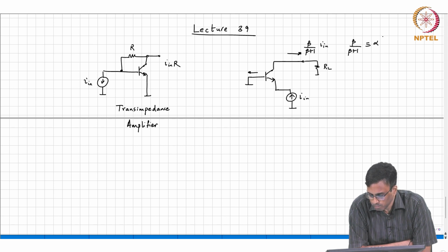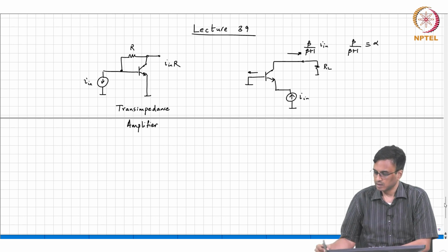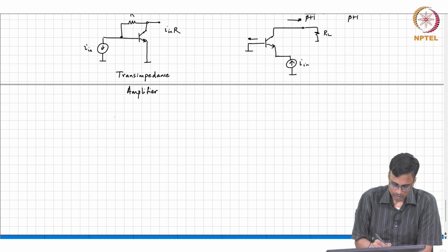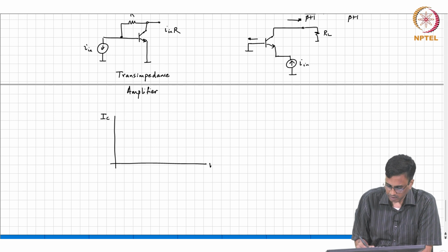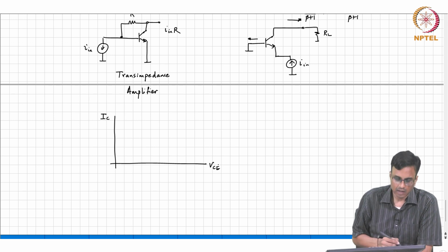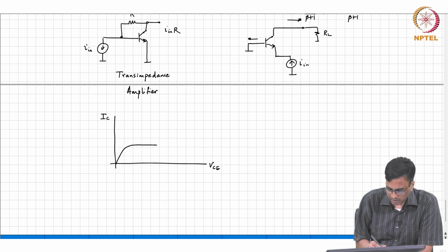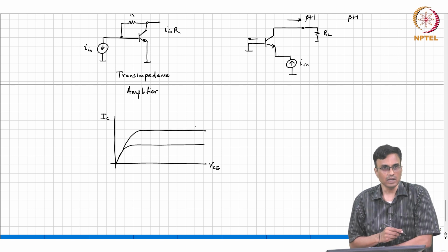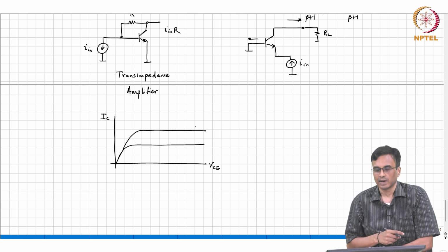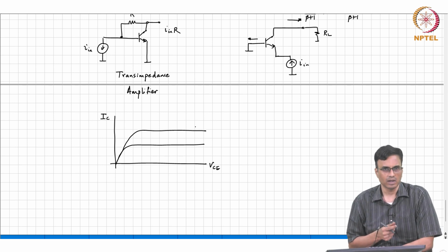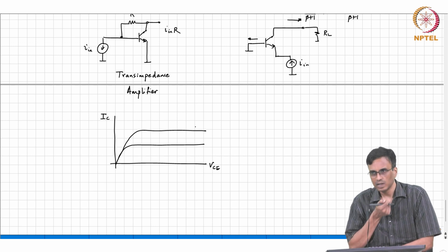Now, like in the MOSFET case, for the true transistor, ideally the output characteristics are IC versus VCE for different values of ideally VBE. But remember that the current is so sensitive to VBE because of the exponential. So, rather than control VBE, people find it easier to control IB.